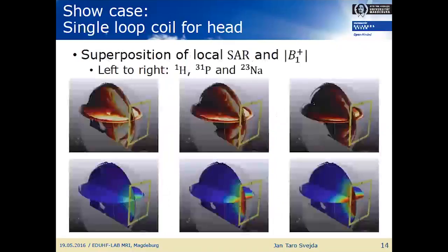And then I also had a look at the fields, so not in much detail. I'm not so interested in the fields itself, I just want to show that it works in OpenEMS. So you see basically that the losses are higher at the high frequency than at low frequency. So here's for 1H, here's for 31P, and here for 23Na, sodium. And the B field, or the B1 field, which I calculated, is higher for the lower frequencies.